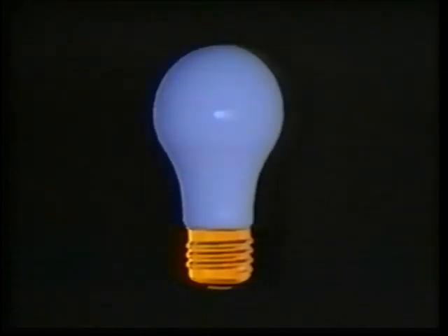The construction of a lamp determines both the amount and direction of the light it produces, but it can also affect the quality of the light itself. Clear lamps produce the highest output per watt, but the light can be very harsh. That problem is solved when the bulb is frosted inside. Etched with acid, the glass is made translucent with only about a 3% loss of light. So soft white or white satin lamps provide almost as much light as a clear bulb, but are much easier on the eyes. Colored lamps are created in a variety of ways.